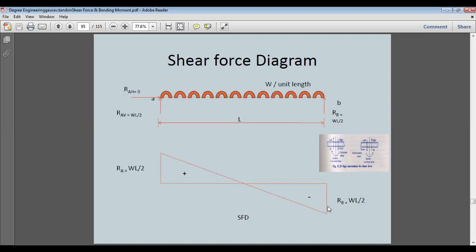So we'll be representing the loads and the moments in equivalent dimensions. If this is 10 newtons, we'll draw a line from here to here, 10 millimeter, or any other dimension that is convenient to put on the paper. So this way we'll have the 10 millimeter.